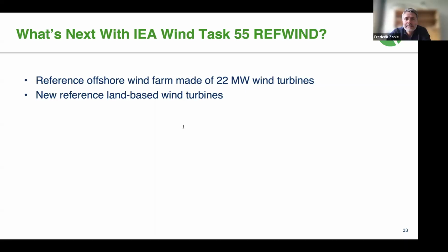What else do we have? There are a few questions about the mooring system. We use kind of the same architecture as the 15 megawatt: the 3-line catenary mooring system. That 400 millimeter chain diameter, I don't think is right. I've got it going up from 185 millimeters at the 15 megawatt to 225 for this 22 megawatt machine. But we already got some feedback that those line diameters probably don't exist. So we're looking into alternative mooring configurations, and we did not include fatigue there. That's an interesting design challenge that we left out of the scope here.